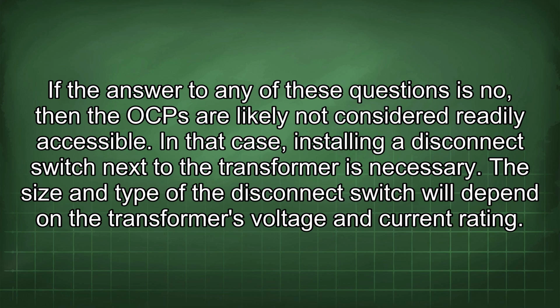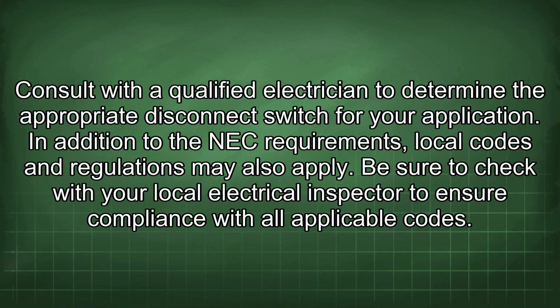The size and type of the disconnect switch will depend on the transformer's voltage and current rating. Consult with a qualified electrician to determine the appropriate disconnect switch for your application. In addition to the NEC requirements, local codes and regulations may also apply. Be sure to check with your local electrical inspector to ensure compliance with all applicable codes.